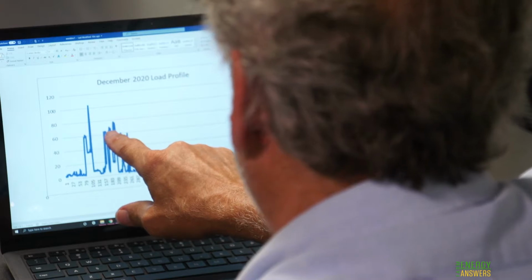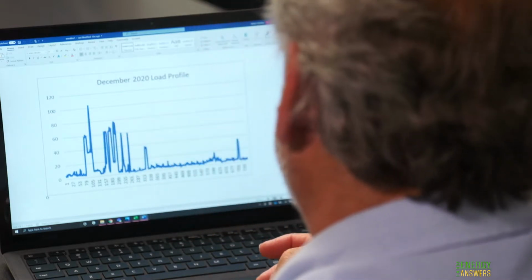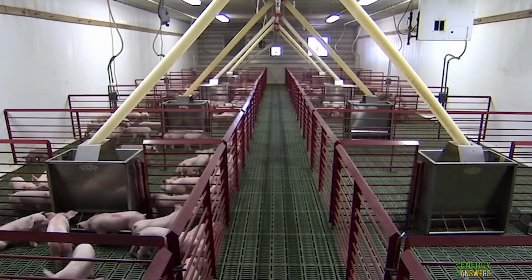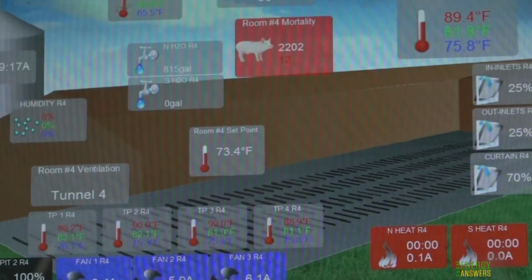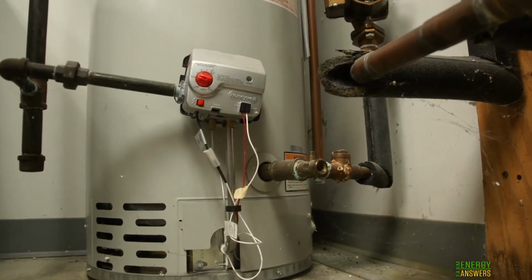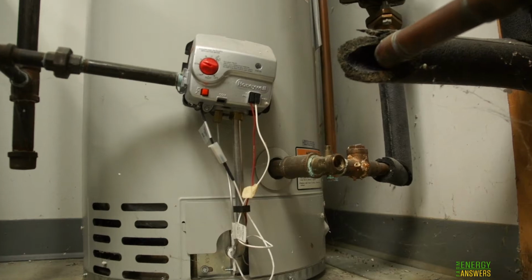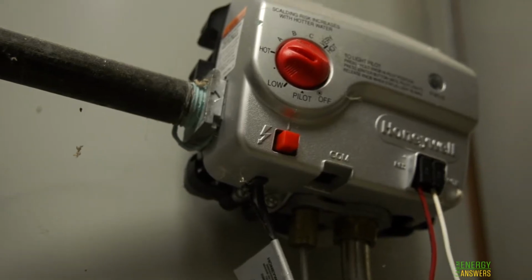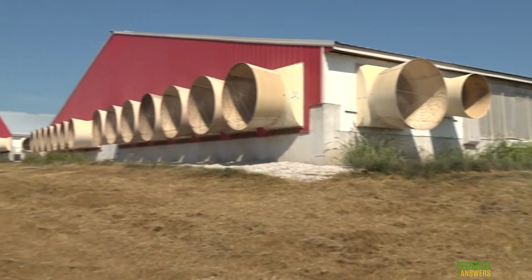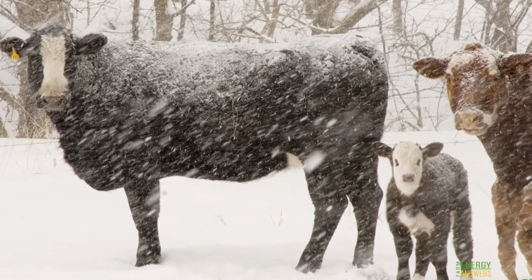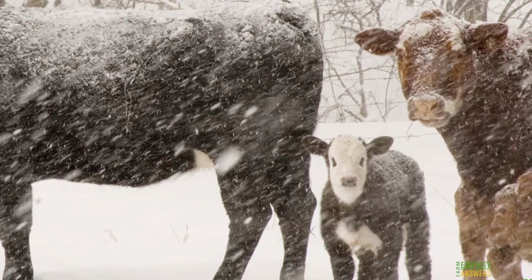Look for any unexplainable jumps or drops in the EUQ. The energy use quotient will spike up or down depending on changes in operation in the farm. Sudden increases can be indicative of faulty or shorted heating elements, a defective temperature or pressure relief valve, leaks in plumbing or faulty valves, resetting of set points perhaps after a power outage, and theft of energy. Probably the most important one is changes in seasonal activity that cause greater increase or decrease in energy use.